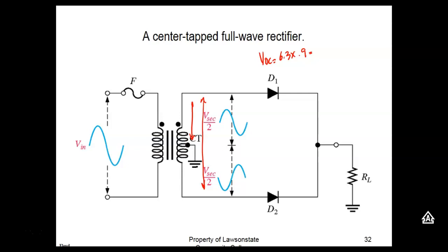And like I said, guys, on a center tap transformer, that is where we have the most problems, when they give the rating of the transformer as a 12.6 volt center tap transformer, then you try to use 12.6 volts. But it's center tap, which means we're only using 1/2 of it at a time. So instead of using the 12.6, we're going to be using 6.3, which is what we should expect. And what's this? Anybody got it yet? About 90% of that. Which is good.